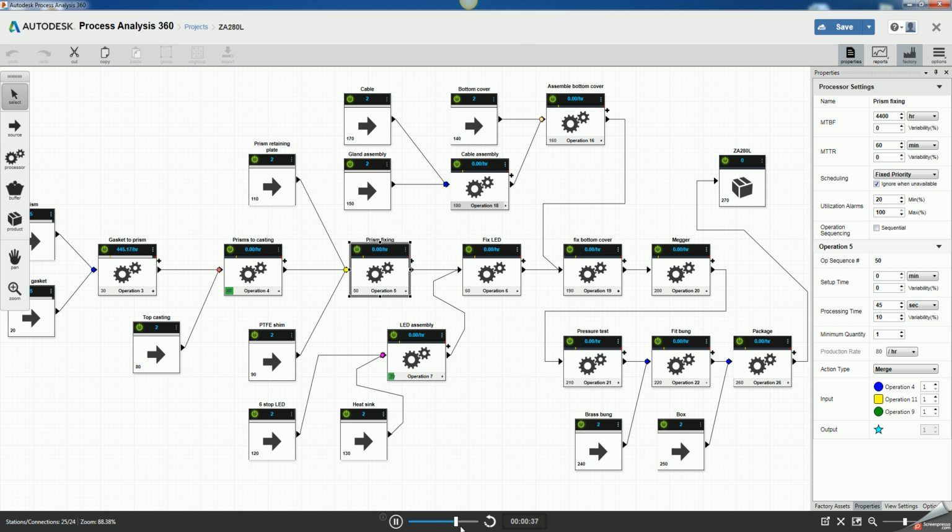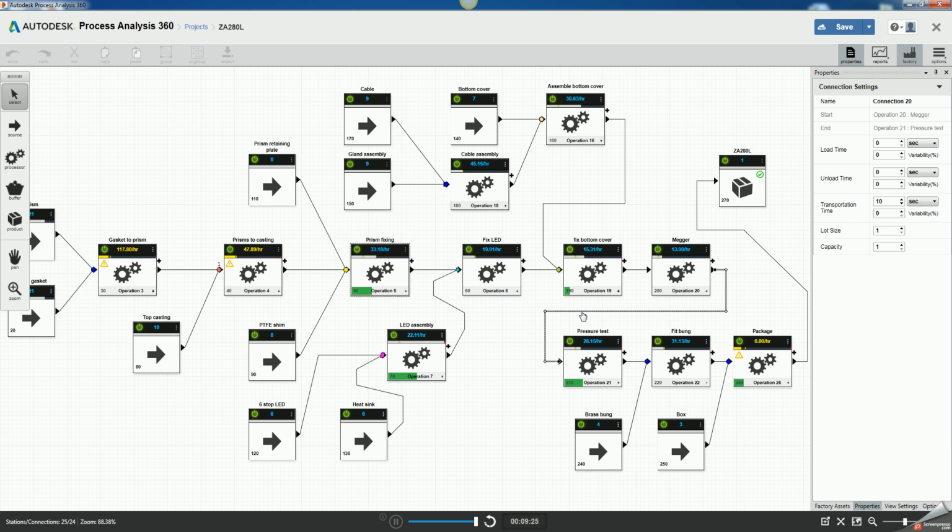And we can also speed up the replay time. You can see it all working through the process until we get here. We've got 1. So we can see from start to finish we have 9 minutes and 25 seconds. This whole table took about 20 minutes to set up, and there are quite a few more tweaks we can put in, so some of this transportation time we've still got set as the standard 10 seconds.